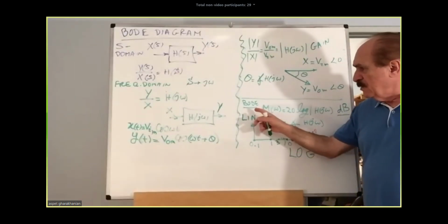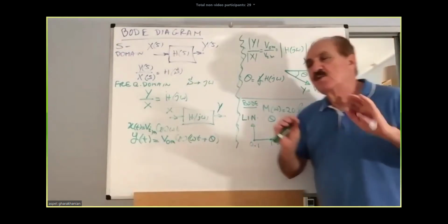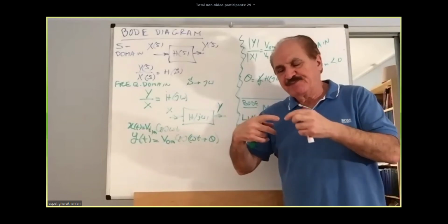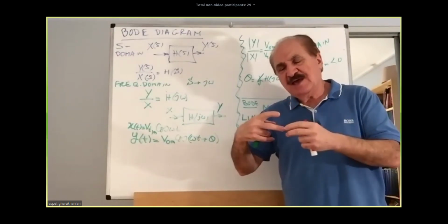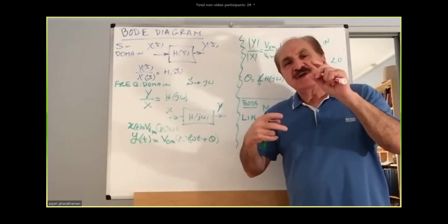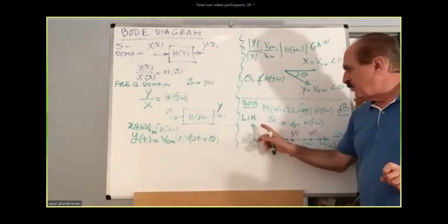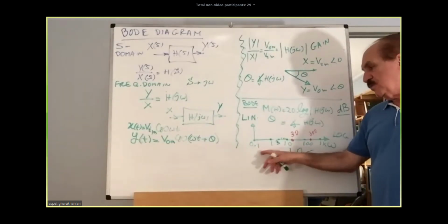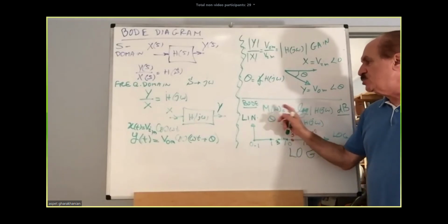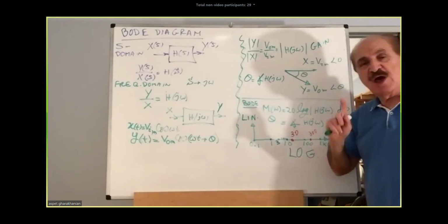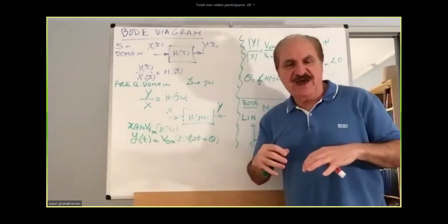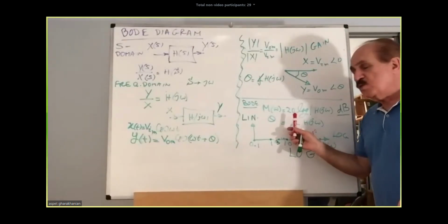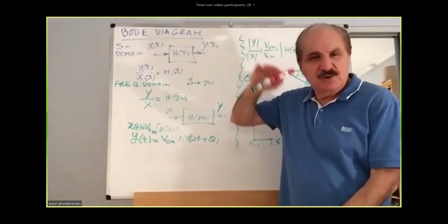So Bode plot, however, is the term given to a unique frequency response consisting of a gain and the angle. The angle versus the logarithmic scale frequency is called phase response, which we'll discuss. The magnitude, however, is not just a straight plot, but rather 20 logarithm of that will be plotted. And that is called the gain response. Also, when you 20 log something, you compress it.